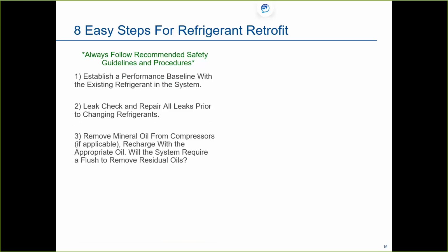Remove mineral oil from the compressors if applicable. Recharge with the appropriate oil. Will the system require a flush to remove residual oils? Again, on our 9311, you'll see all the refrigerants and oils and what they're compatible with. It'll actually point out to you, all of our compressors, for the most part, are going to